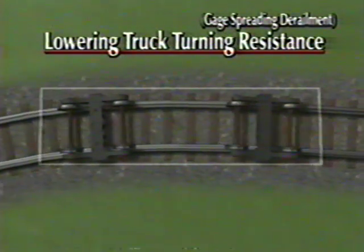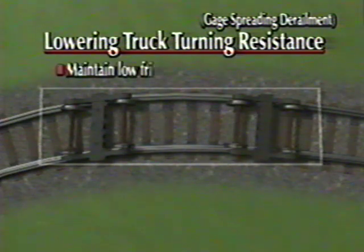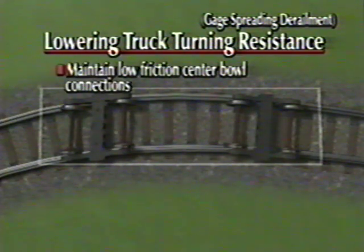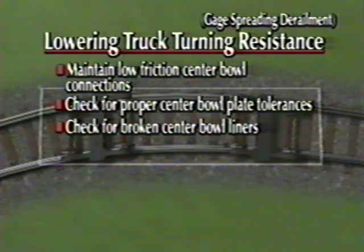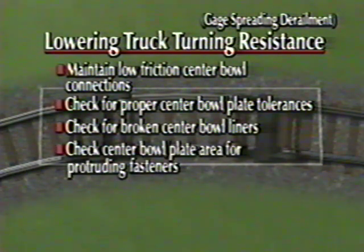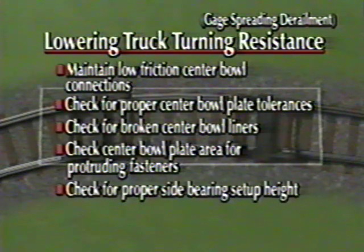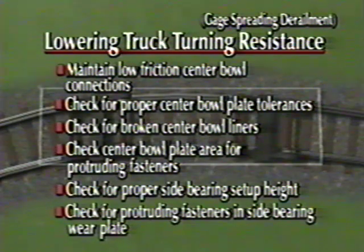Let's review the factors that lower truck turning resistance, like keeping center bowl friction low, checking center bowls and center plates for proper tolerances, checking for broken center bowl liners, inspecting the center bowl center plate area for protruding fasteners, checking for proper side bearing setup height, and inspecting the side bearing wear plate for protruding fasteners.